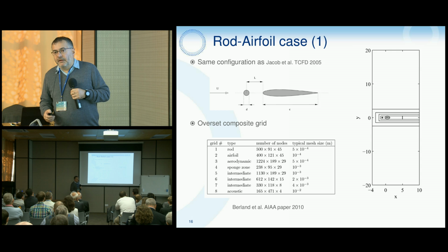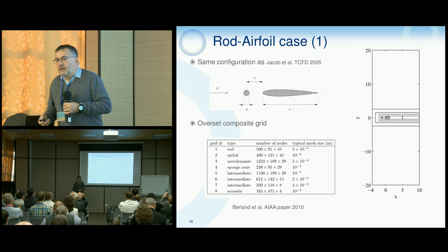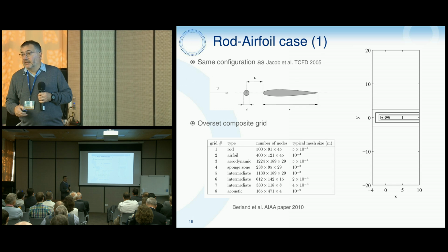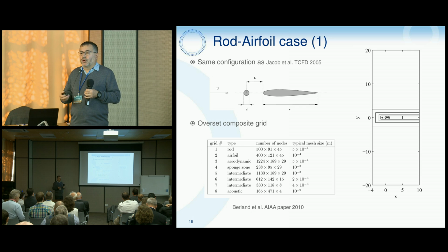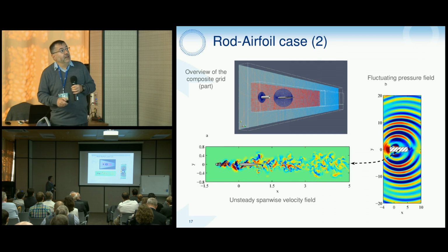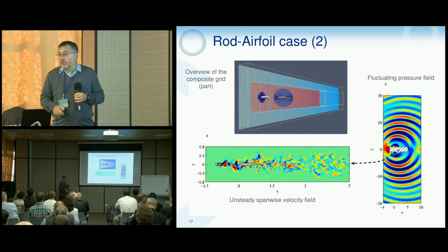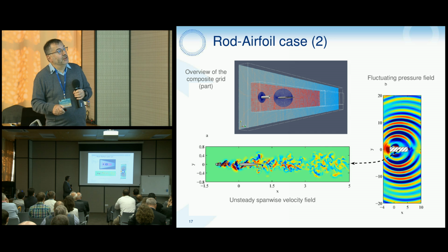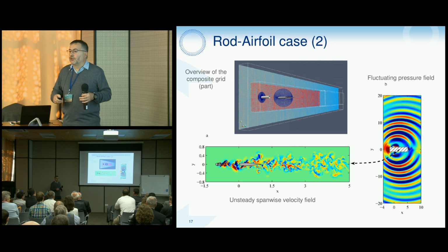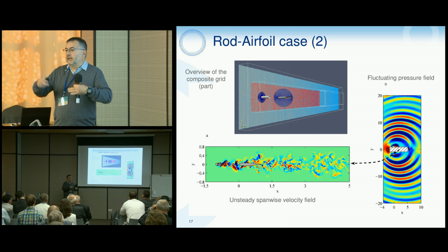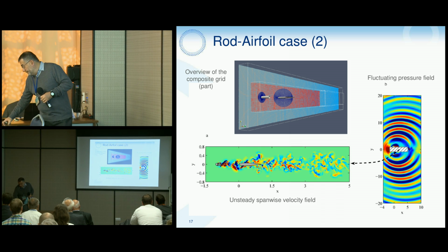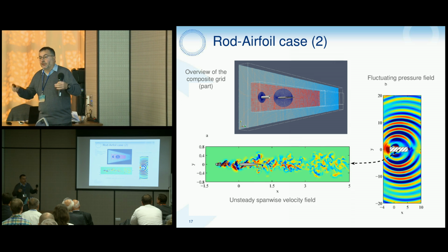We were also, for a while, interested in rotor-stator interactions in the steam turbine. So, in fact, we found this classical test case in the aeroacoustic community in order to try to make some calculations in this approaching case. So here is the kind of mesh, the grid we built. Here we have the velocity field, and here the pressure field till the far field. It also illustrates the capability of the overset grid, because you can have a fine grid around the bodies and then a coarser grid for the far field propagation.